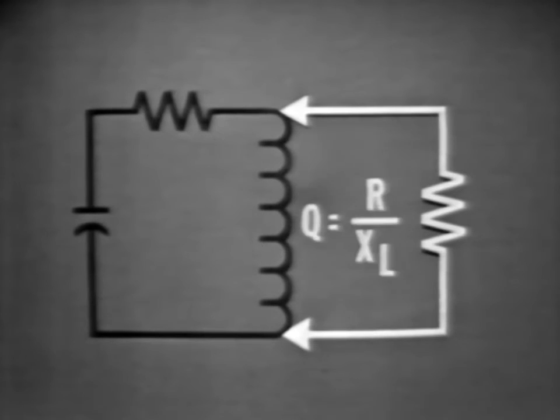However, there is another quality factor that concerns external circuit resistance, and in this case, the resistance should be high. In other words, the amplifier connected to the frequency-determining device should offer maximum impedance to the tank. Even then, there will be some energy loss to the external load, which must be regained by increasing the feedback.